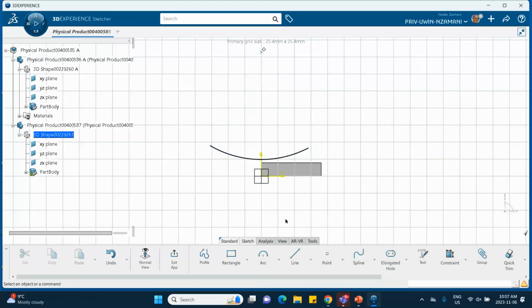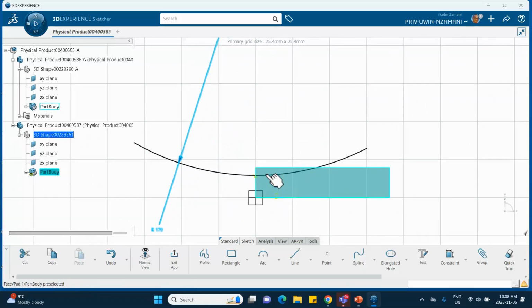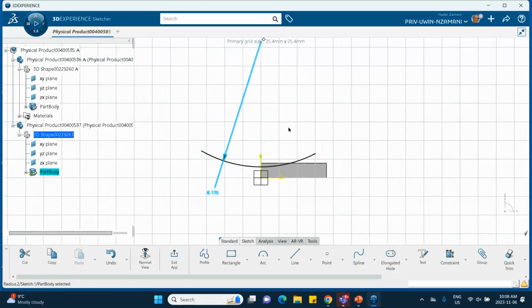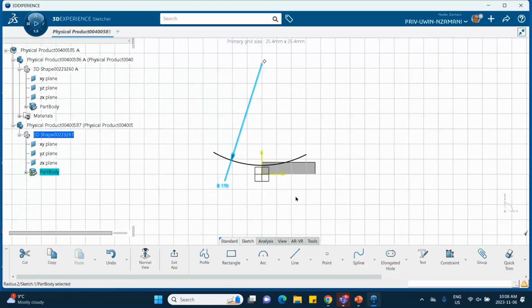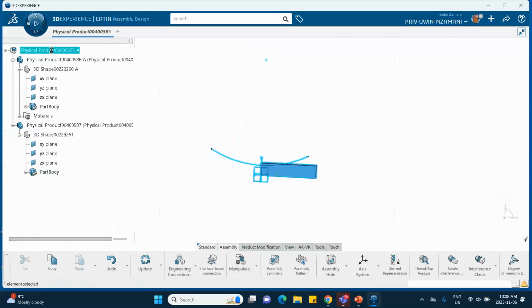Okay, let's dimension this. The radius of this drum is 170 millimeter right there. Notice that it's interfering, which is good because actually this block has to go through this. Okay, all right, so that's taking care of that. And so I don't need the material on that because it's going to be an analytical rigid surface. Okay, so we go all the way to the top.